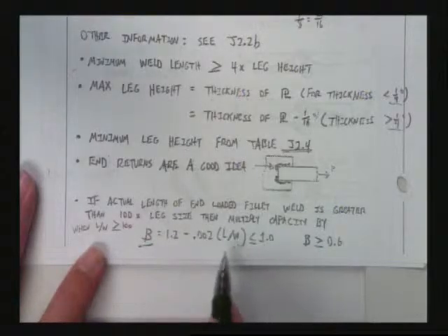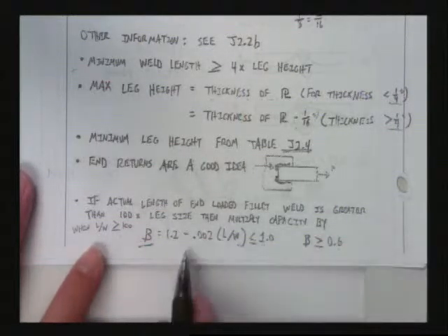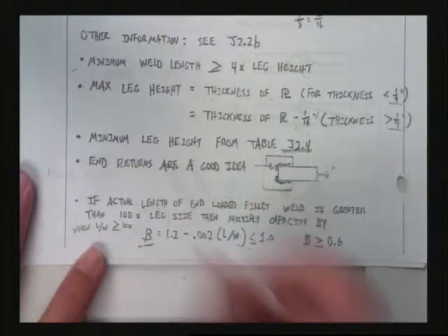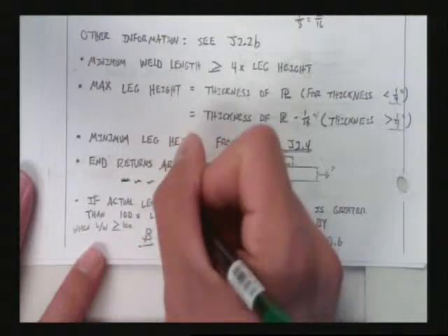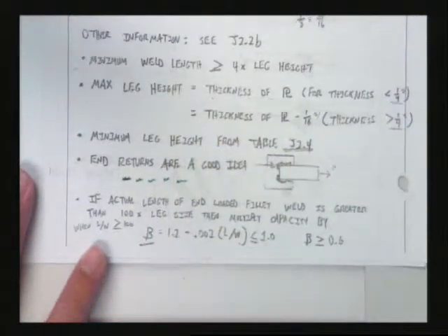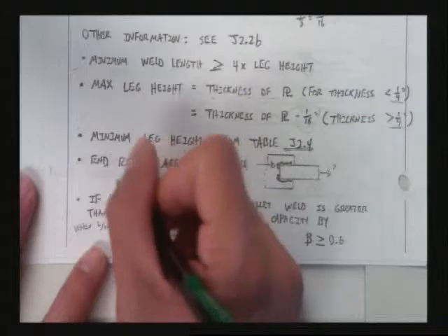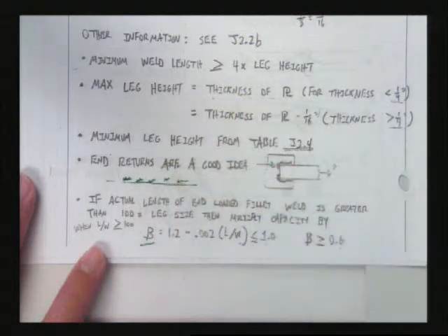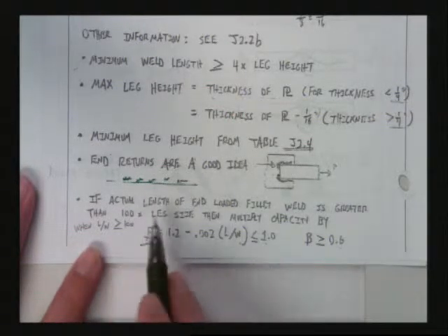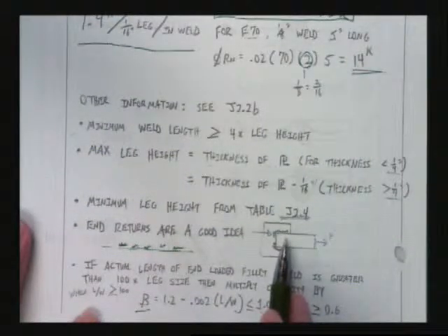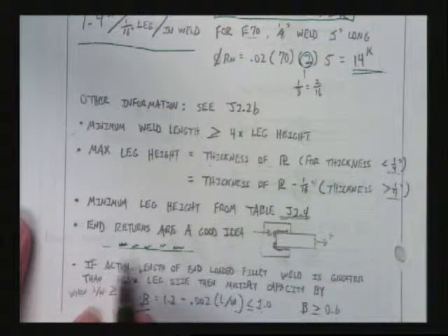And oftentimes what people will do is they'll try to use things called stitch welds. What a stitch weld is, if I'm hooking two plates together, I have welds that look like this. Two plates together. And if you're ever at the stadium here on campus and you're walking up and down the stairs, whether it's the basketball or the football stadium, you look up on the stairs, you will see stitch weld, stitch weld, stitch weld. You often see a lot of stitch welds all over the place. You really start to look for it. The reason why is because people don't need that entire length of weld to get the capacity. They're so strong. So instead they use stitch welds.